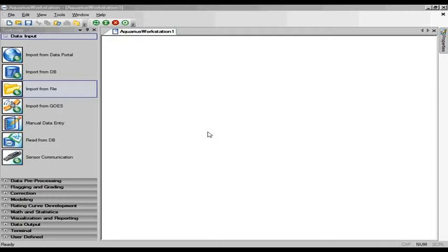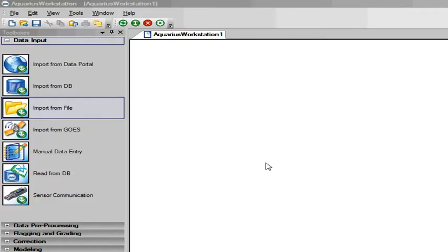Now typically this data might be collected by going out into the field, say once a week, dropping a sonde over the edge of a boat in a lake or in a reservoir, letting it down to specific depths, taking measurements at those depths, and then bringing it back up, taking it in, and then a week later going back and performing the same type of survey.